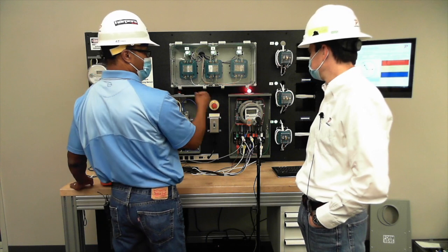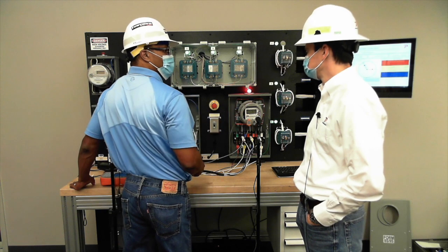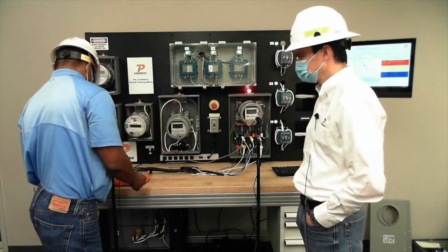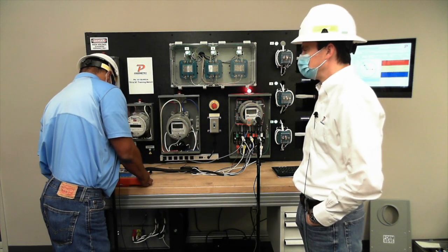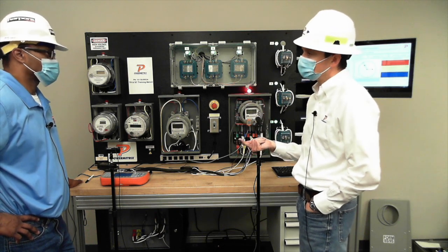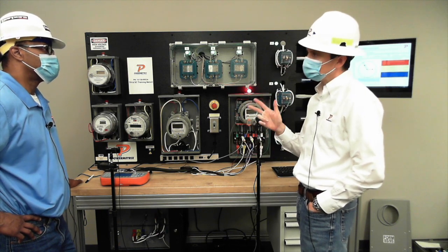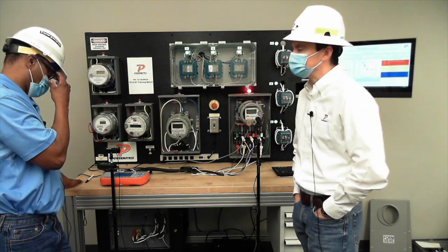Yeah, just like a demand, if I test that meter as demand, and it's set up for 5-minute demands, and you're asking for 15-minute demands, and you get some type of inaccuracy, check with the programmer to see how it was programmed. Right. But anyway, we're going to put a 1 there. If the meter technician has time, it is always good to interrogate the meter to make sure the program is correct. Yeah, we have seen a lot of programming errors: wrong Kh, wrong CT-PT multipliers plugged in, wrong demand interval. So there can be programming errors right off the bat.